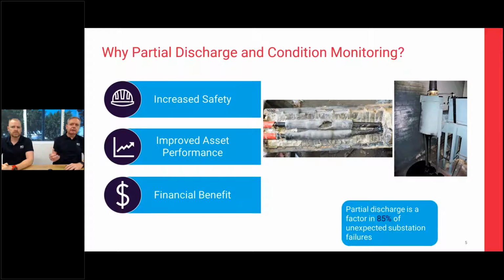When we're talking about the terminations in the switchgear, in the substations, then of course the safety aspect can become significant. You can see the picture on the right in this slide: an old compound insulated cable box which has exploded. If we're in the substation at that time, then obviously we've got a safety aspect. The picture in the middle is of a joint that has failed. If that fails, it's directly buried, it's underground, so we're not realistically going to get much of a safety impact. We're going to get more of a network performance impact.